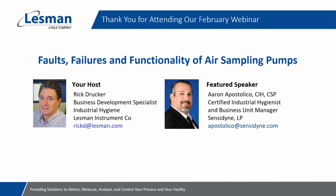Yep. So, the pumps are made to sample in hazardous areas and environments. Obviously, you don't want to douse any type of solvent onto your pump itself. But in general, if it's just there and it's air sampling, it's going to get absorbed onto your charcoal media or your silica gel media. They're made for that. Most of the pumps, especially the low flow pumps, have certain hazardous area approvals to make sure that they'll work in those hazardous areas.